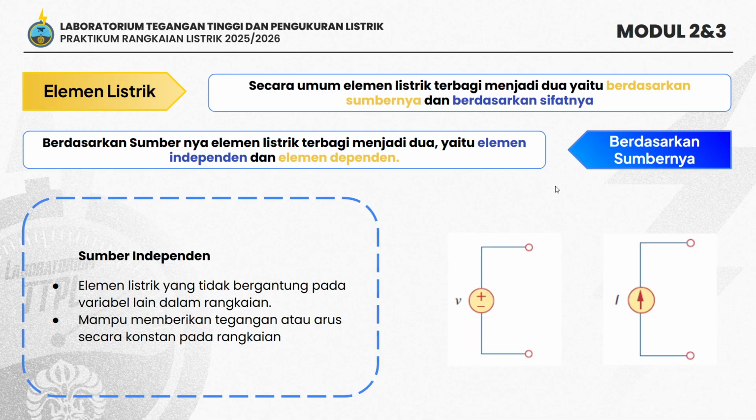Next, let's discuss electrical elements. Electrical elements can be classified based on their source and properties. Based on the source, it can be divided into two, which is independent source and dependent source. Independent sources are elements that provide constant voltage or current regardless of other variables in the circuit. They are usually symbolized by a circle.